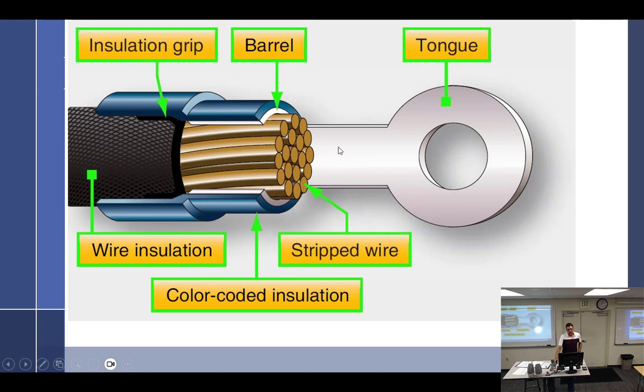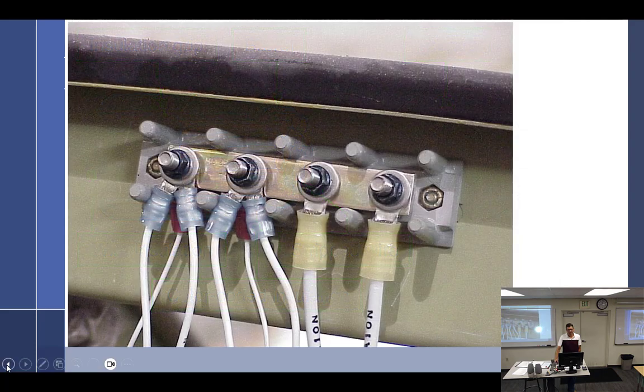The idea is, this is funny, in automotive we crimp it right here, but in aviation it double crimps. It crimps once on the insulation and once on the barrel. So you're crimping onto that Teflon insulation. It's really tough to pull these things apart, and that's the whole idea. Why don't we do that everywhere then? Because these crimpers cost a lot of money, and they're calibrated.